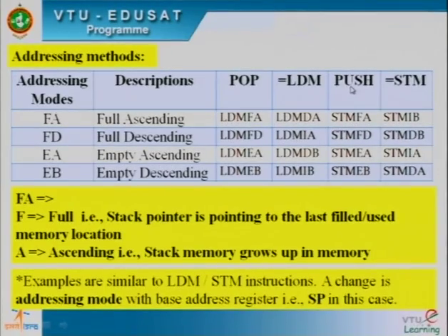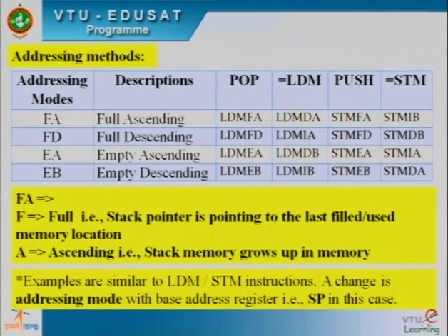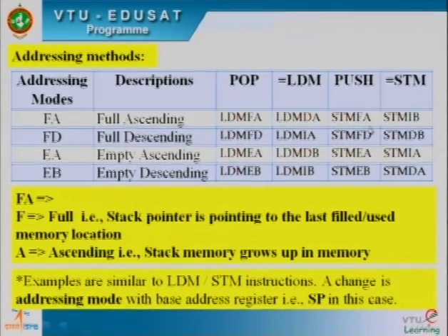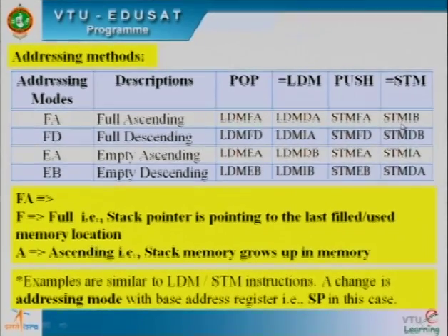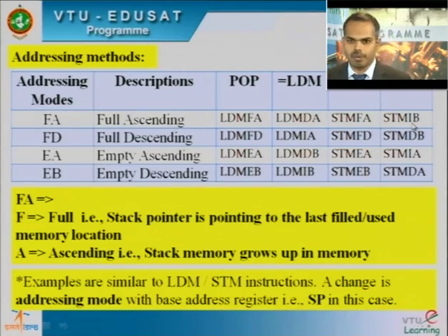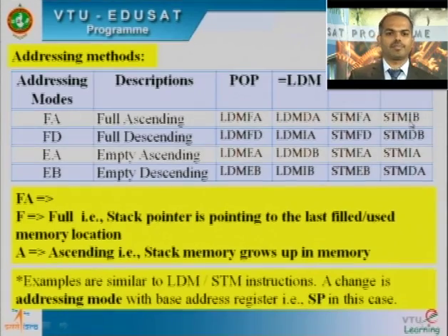Now the push instruction. The push instruction is like you are pushing the register value to the stack memory. With that, again STMFA, that is full ascending stack. With the help of the full ascending stack, store the register values in the full ascending stack. That is the meaning of STMFA. This STMFA instruction is executed internally with the help of STMIB, that is store multiple registers and increment before.